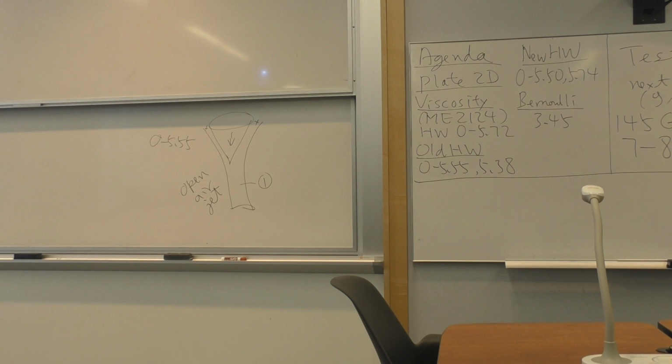So you have now the 2D momentum equation that you need to apply. It seems peculiar area 2 is not given, but no panic. Turns out if you do the momentum equation carefully, that area is not needed. I will leave you at that. But the momentum equation is fairly straightforward. It's actually a 1D problem because the only thing that is of concern to you is the x direction.